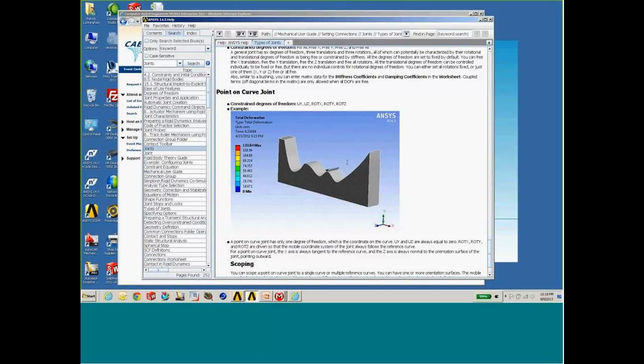So essentially you have, in this case, a curve. It figures out where essentially it is on that curve, and that XY coordinate then becomes the degree of freedom setting for that joint. So kind of an interesting way to put an arbitrary range of motion or direction of motion on your joint features.